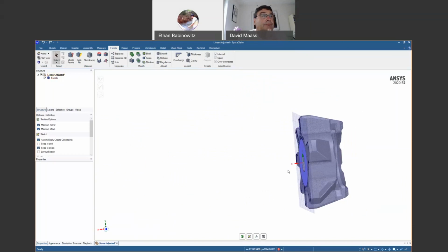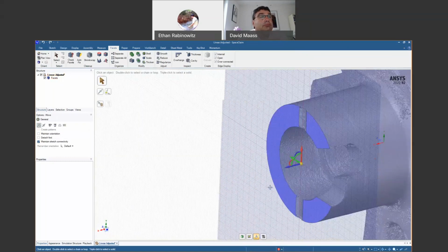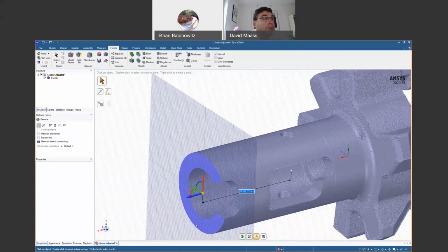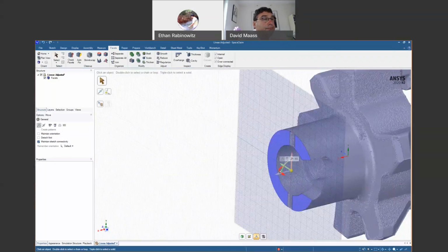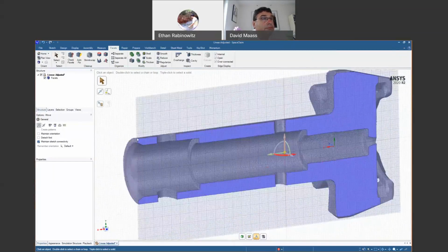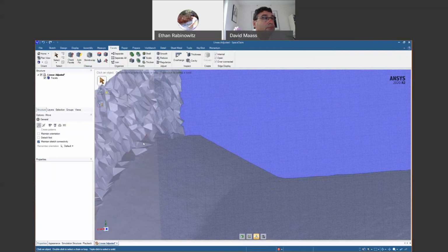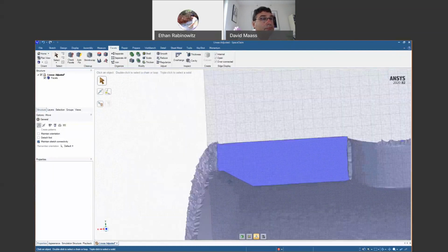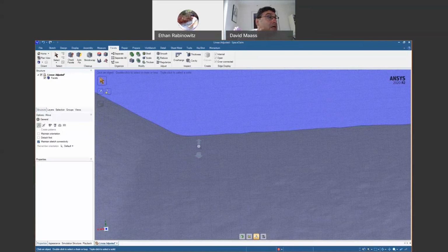Another direction we could head in would be looking at cross sections here, because you can see that as we go through the model in this direction, we can often see the diameters change and get bigger and smaller. And so if we capture those as circles in each direction at each size, that's one way to build up the model. Or if we look at the model in this orientation, I may sketch out or extract curves. You'll notice in some areas, I may look at this and say, all right, I know it should be flat on the end, so that is accurate. Or maybe I look at the triangles and I think, well, maybe that chamfer is actually supposed to extend all the way to the front face, because I know how it's going to be used in the assembly, and it should have a nice lead-in all the way, or whether there are rounds there. I think I understand that.